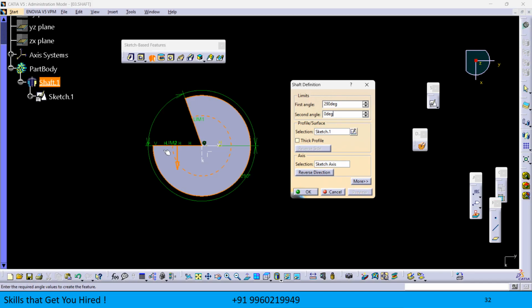If you use the second direction and you try to rotate this second limit, material will be added around the clockwise direction. So here, if you see, this limit is 20. So the first limit and second limit indicate the clockwise and anti-clockwise direction of rotation. Now here you define the second limit 0, and my first limit I am considering here 360. Then accordingly the material will be added with a complete 360 rotation.